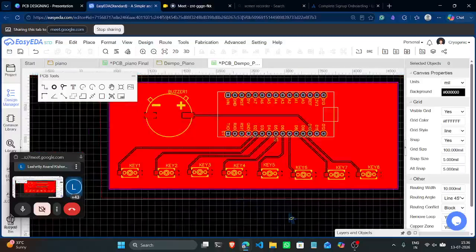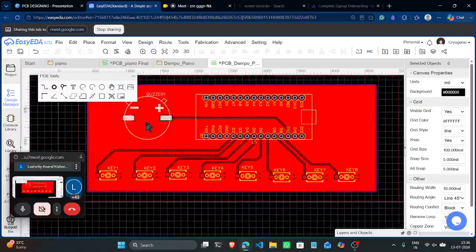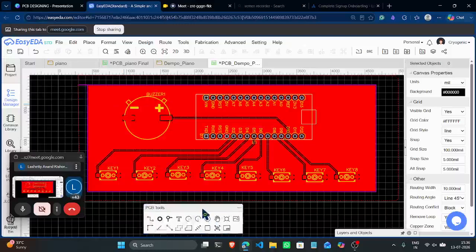And there are many different uses with this ground plane. It will effectively distribute the heat everywhere. Think of a ground plane as a trace, a big trace having longer length and also a wider area, so the resistance will be really small. Since power planes carry a large amount of current, less heat will be generated because the ground plane is really huge, I mean, it has less resistance. I hope you understood that.